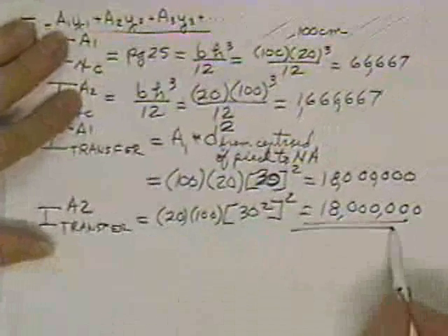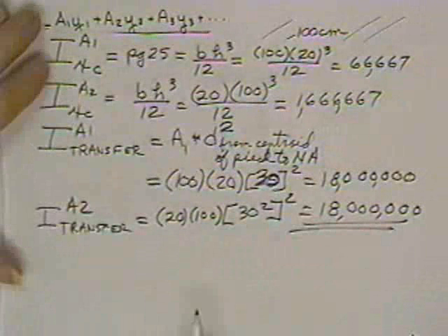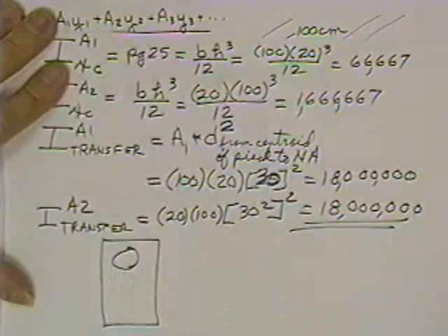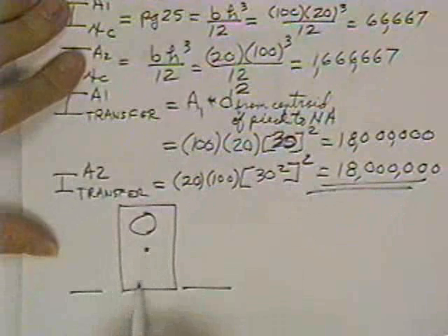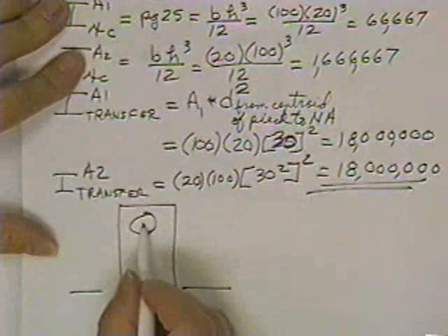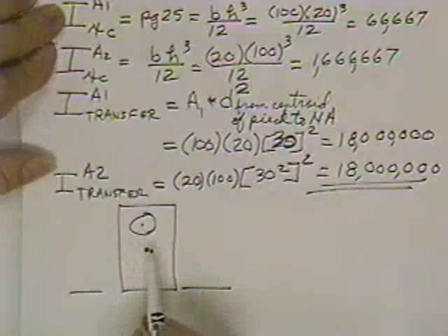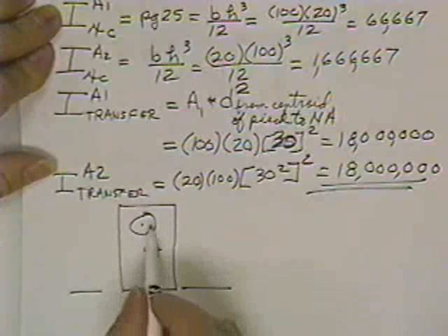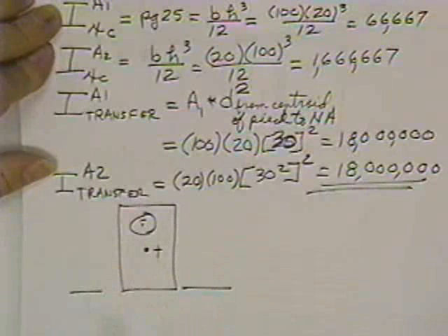All right. And then all you do is add them all up. They'll always be positive unless the area is a hole, like a missing piece. So if somebody gave you this, you would draw a reference axis, you would take area 1 as a positive area, then you take this hole as a minus area, and you'd solve for where the centroid is. When you did the moments of inertia of each piece by itself, this would be a positive area, and therefore a positive moment of inertia. This piece would contribute a negative.